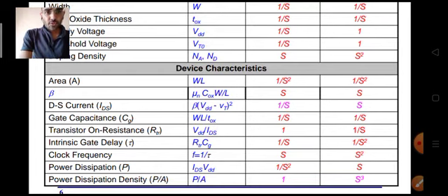Okay. Then gate delay. So if we talk about delay, it is intrinsic delay. It is whatever delay we have for the gate itself, without considering your wire interconnects. So if you consider the delay of the gate itself, then it will become something like this, affected by substituting the values from the upper cells. So that's what we have to do. Then frequency. For constant field scaling, it becomes multiplied by the factor s. For constant voltage scaling, it becomes multiplied by s square.